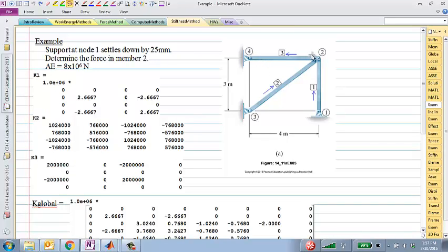So this is a 3 element truss. First question, is it determinate or indeterminate? Indeterminate. And to what degree? How many say 3? How many say 2? How many say 1? It's to degree 1, because if you cut any of those elements, it becomes a determinate truss, right?